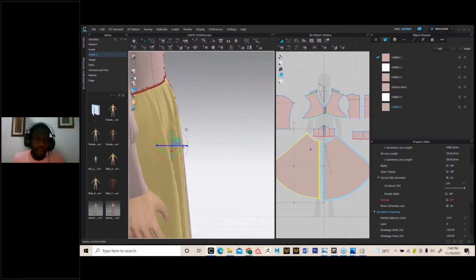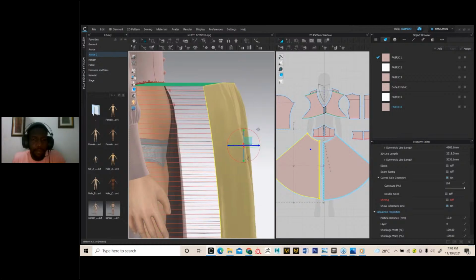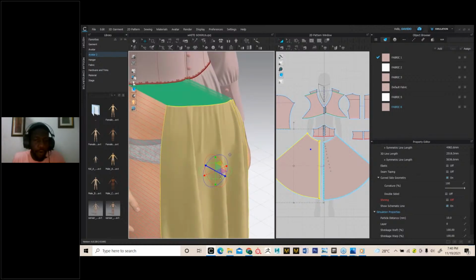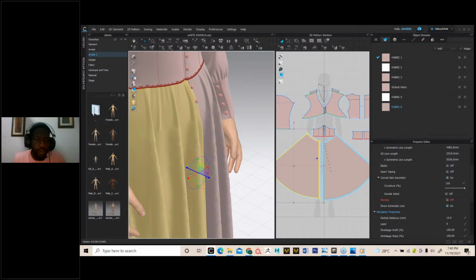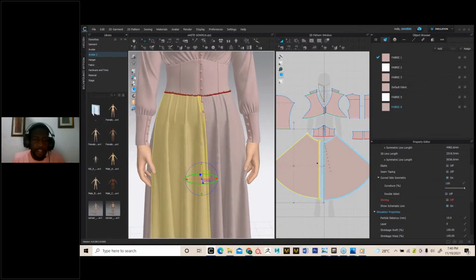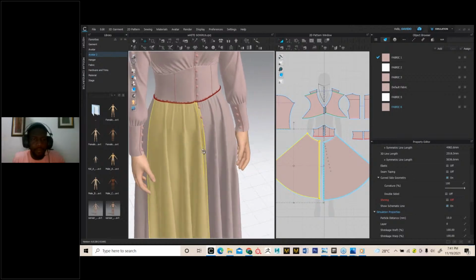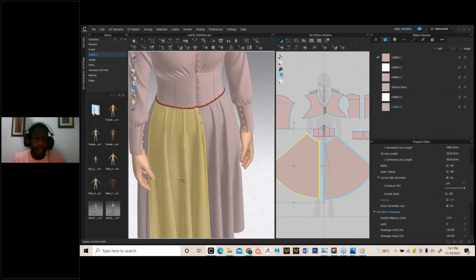So if you want to move forward, for instance, you click on this blue arrow because it is showing front. The blue arrow is also known as the Z-axis. Once you click on it, you can see I'm moving forward. If I click on this red arrow and try moving, it will move horizontally, because the red arrow is facing the horizontal direction. So you can only move this way and this way using the horizontal direction. Perfect. So that is about the gizmo tool.